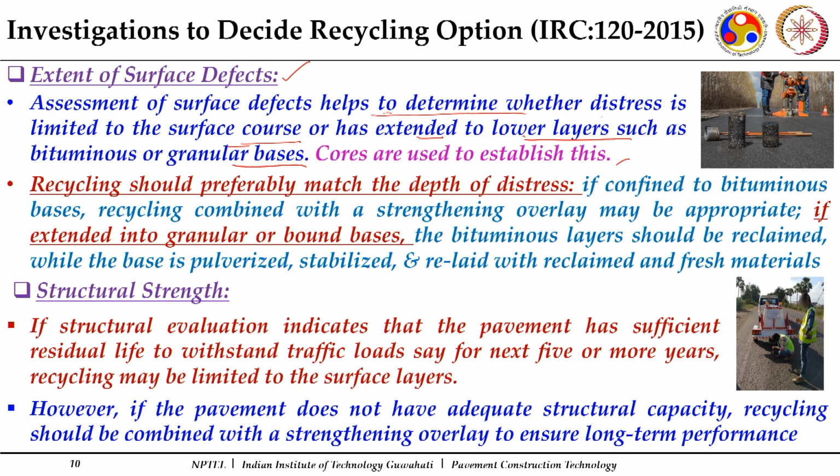For this you can do coring, you can cut trenches and see the extent and type of distress as well as the layer which is involved. Recycling should preferably match the depth of the layer which is having the problem.